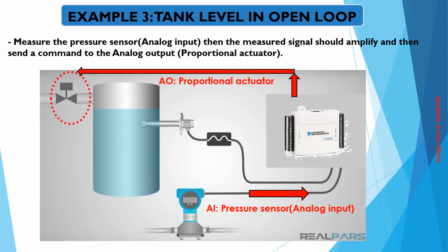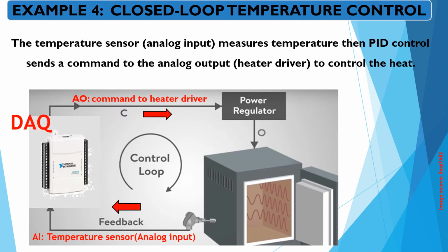Then we will discuss the tank level in an open loop system, how we can implement an open loop system in the MATLAB environment, how we can connect to the data acquisition system, and how we can measure the physical environment such as the level sensor or pressure sensor, connect to the data acquisition and monitor in the MATLAB environment.